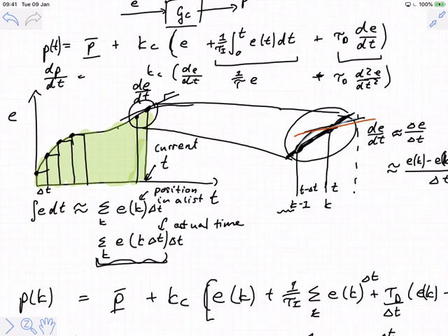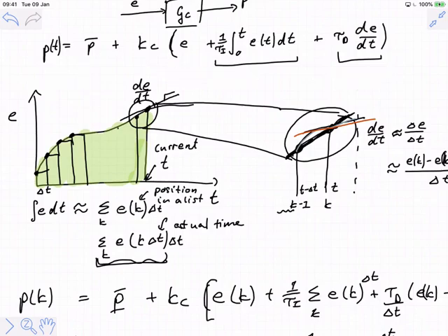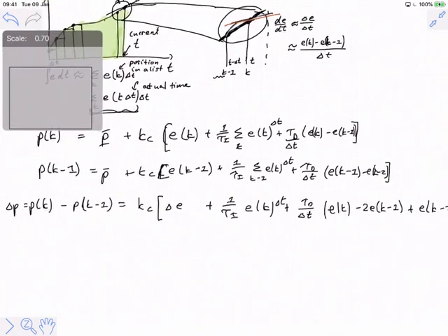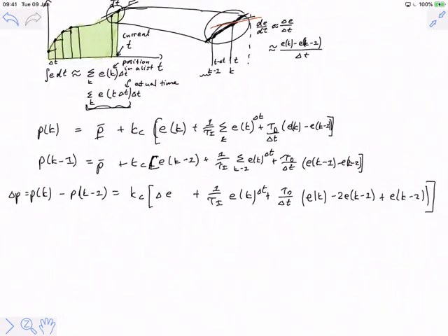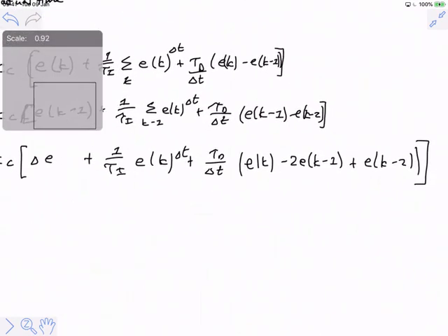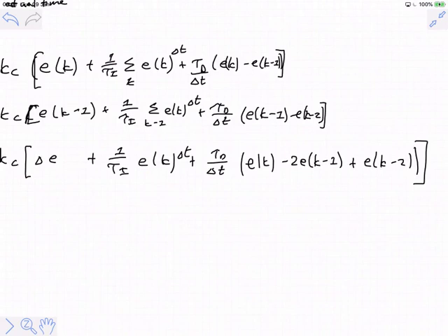Right, so if you just say, well, what if I wanted to find the derivative of that position form controller, you'd see a striking resemblance between that and what you are ending up with over here. So each one of those terms has an equivalent approximation. So now we have our EK and we have our, and this you may recognize as a second order or a finite difference approximation of the second derivative, if you did that in your mathematics classes.